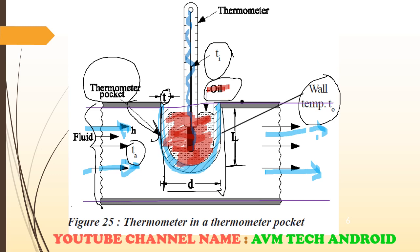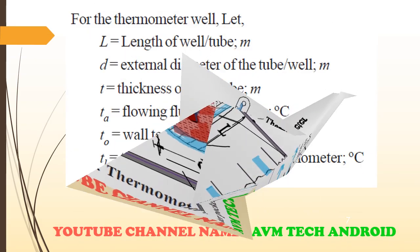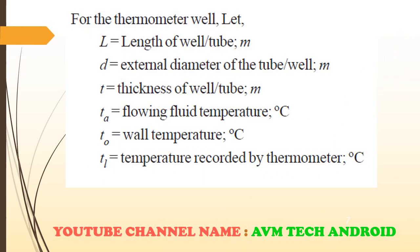This is the oil. So everything we have discussed: this is the thickness. h is the convection heat transfer coefficient. Ta is the temperature of the flowing fluid. D is the outer diameter of the thermometer well. t is the thickness of the thermometer well. L is the depth up to which this thermometer pocket is inserted. Ti is the temperature indicated by the thermometer. So the same thing is mentioned here.